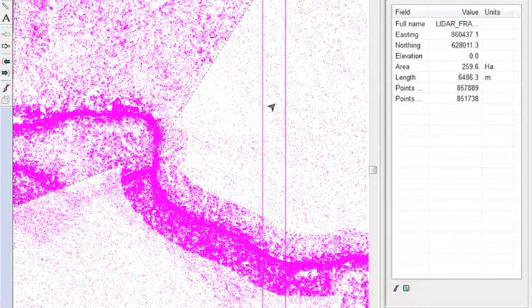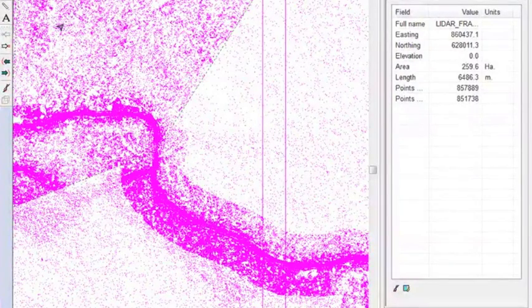And then, of course, the polygon is just denser on the inside. So out here, outside my areas of interest, we're skipping 9 out of 10 points. In here, in my area of interest, we're getting full LiDAR density, and there are only 800,000 points in here, quite a bit less than the 3 million that we would have got if we hadn't done the selection.